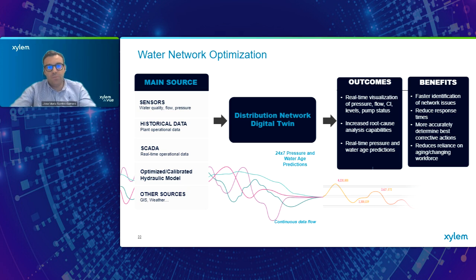So it collects the information from different systems like the SCADA, the hydraulic model, the GIS, etc., processes it and produces outcomes like the real-time visualization, analysis capabilities to spot the root cause of issues, etc. And this, at the end, will produce some benefits for Nashville, just reducing the response time, providing better responses to issues, etc.